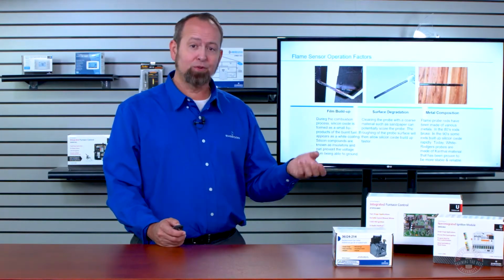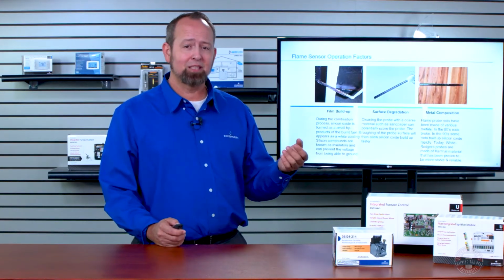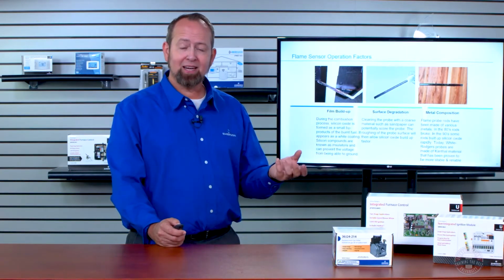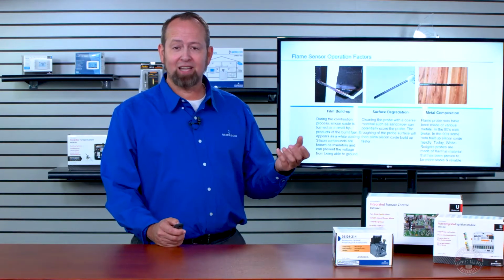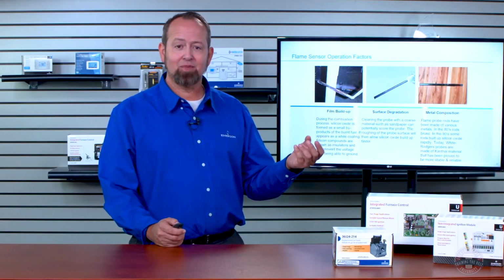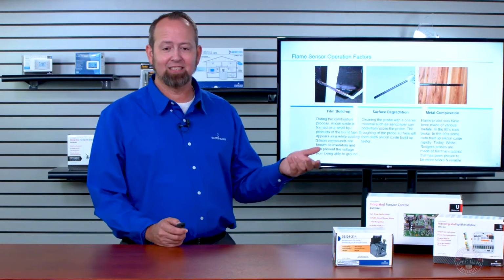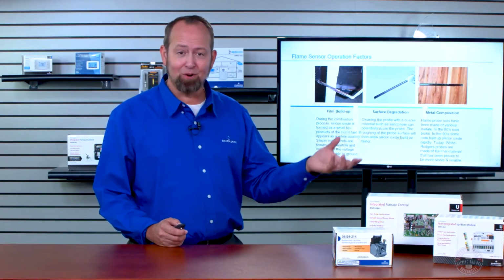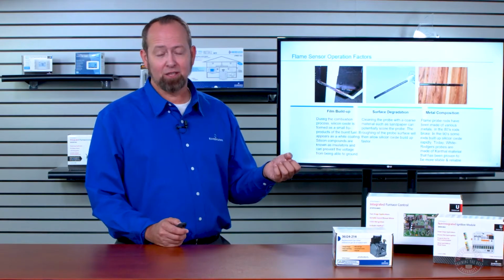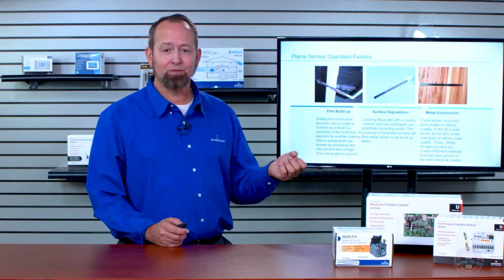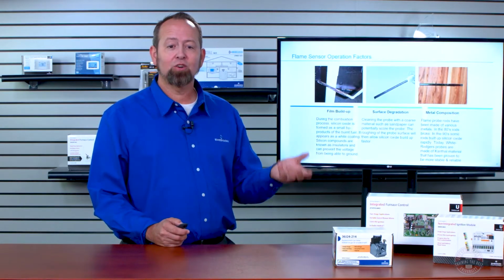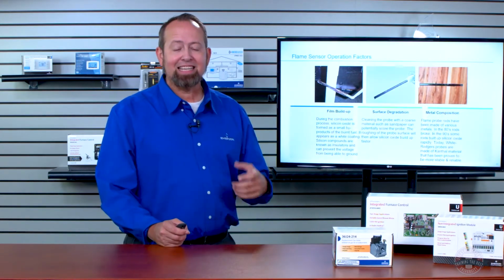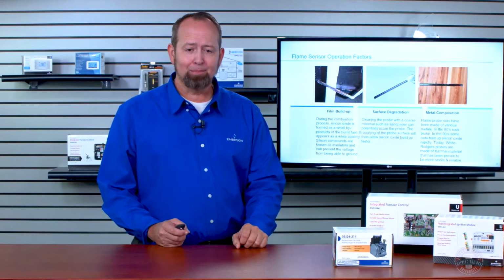The same way with the fuel. We don't see it as much with natural gas, but there's times within propane gas that if there's additives added that can increase this silicon manufacturing process in the burning, sometimes a propane furnace will increase the speed at which that silicon oxide is built up on that probe.